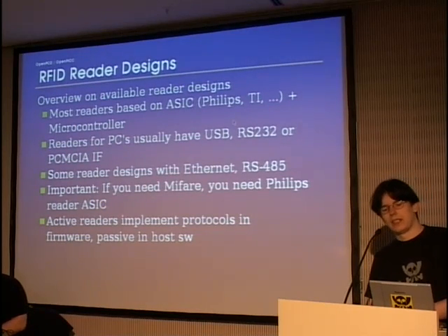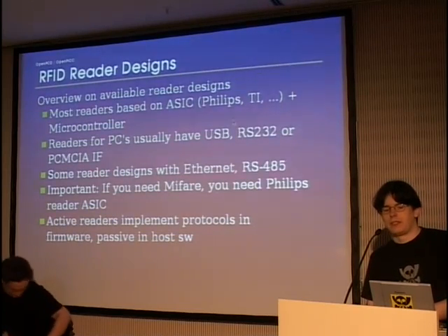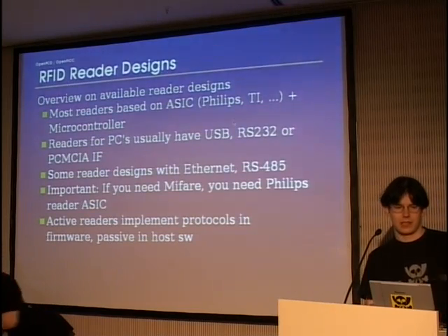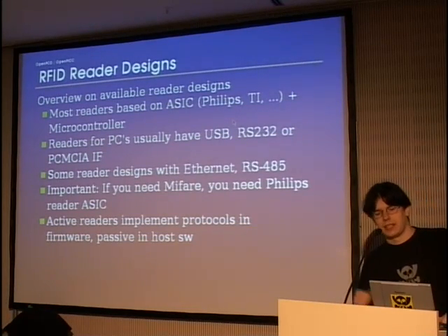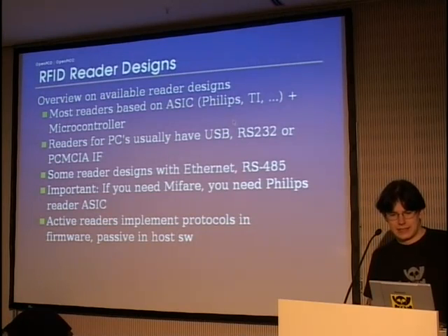Also Texas Instruments, and a microcontroller next to it. If you have readers that are not standalone devices, so readers that you can attach to a PC or something, you will have a USB interface, you will have a serial port, or you have PCMCIA, compact flash, whatnot. There's also some reader designs which have Ethernet or even RS485 or similar protocols.